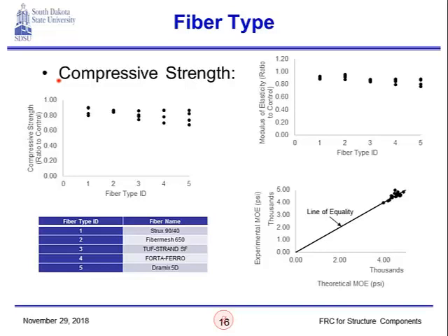I believe we need further studies focused on compressive strength to be able to identify the reason behind this drop. But in our procedures, based on what we adopted and followed, we couldn't identify the reason behind this drop. But it's something that should be noted, and whenever you design FRC, you should note that you might lose some compressive strength, until further studies are made on this specific property.